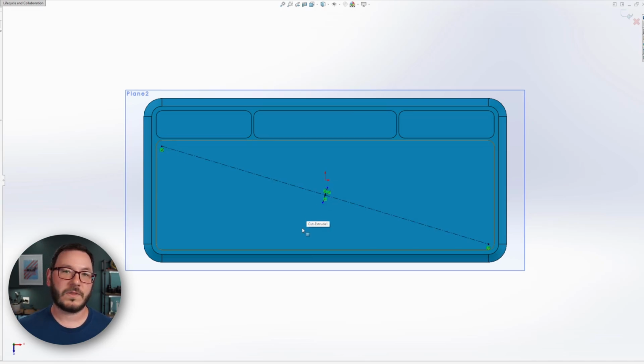Now at this point, we have everything that we need. Now, normally you would be saying, hold on, we didn't fully define our sketch. If this makes you queasy, you can go ahead and fully define this. There's not a problem with fully defining this, but for the sake of purposes with the rib, we have an interesting scenario that's a little bit different than most of our features that we're creating in SOLIDWORKS. So if we take a look at this geometry here, we've got this little stub of a line here. And what is going to happen with the rib tool is it's got an end condition that goes straight down, and it also has secondary end conditions that work its way outwards, so along that linear direction as well.